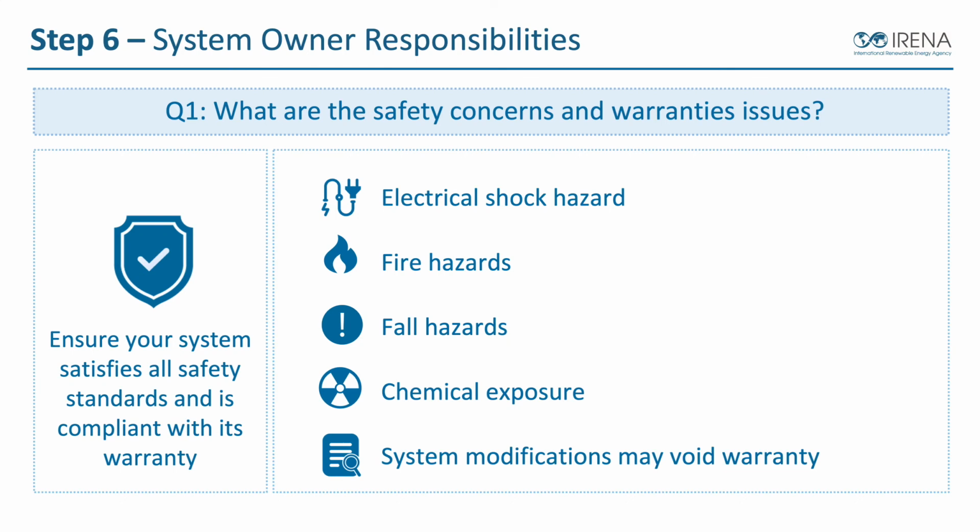Solar PV arrays produce DC output voltage, which can absolutely shock and hurt someone. And a lot of our PV systems, especially as they get larger, can operate at very high DC voltages that are very dangerous, could hurt or potentially kill someone. So we need to be careful about quality of wiring and installations from the contractors. We want to make sure we're looking really closely at the quality of their electrical work. But we also want to think about making sure that either you as a homeowner or anyone else who's going to be around this equipment knows to be safe around it.